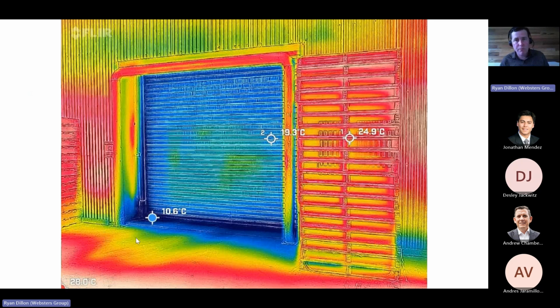So go into your cold room. Is there a visible gap? And then through the use of thermal imagery, if you were to do a type 2 audit, for instance, you can then further refine and pick up some of these problem areas. Also looking for holes and other gaps in the wall, or where you've had a system integrity issue with the cold room structure itself. There might be some air infiltration that you can address through seals in pipes with evaporators, for instance.